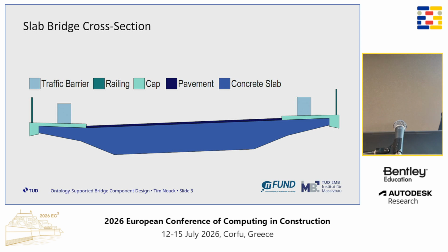the bridge cap component here, that is supporting the railing and the traffic barriers and also the foot and cycle railing. This component is highly standardized, and what I was doing in my automated workflow is to assess these boundary conditions I showed beforehand, then align the cap to the bridge and do the dimensioning of this bridge